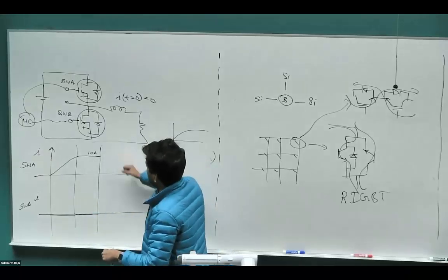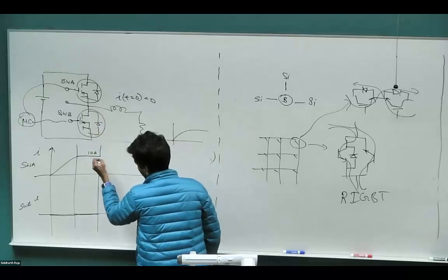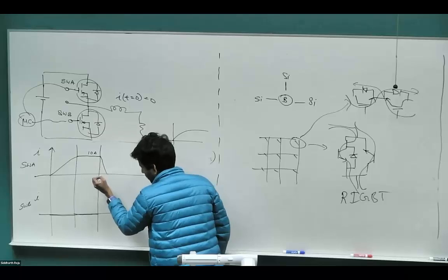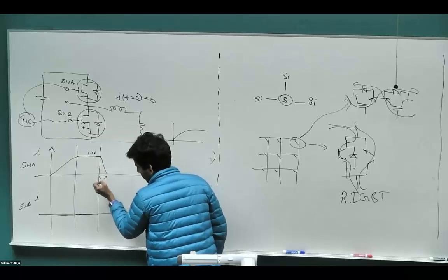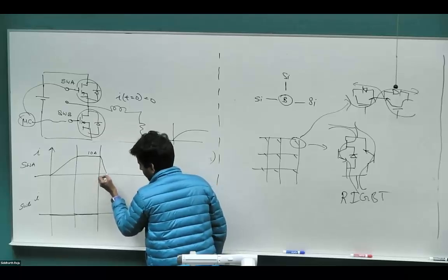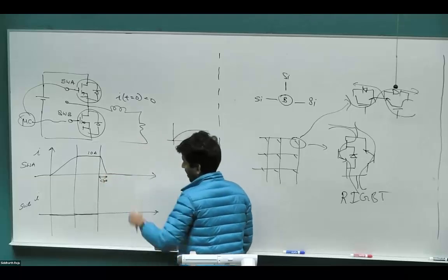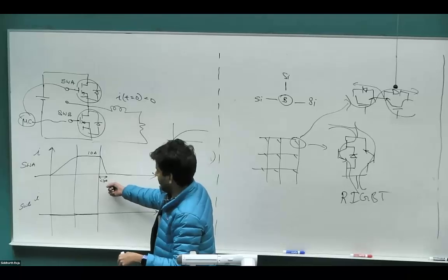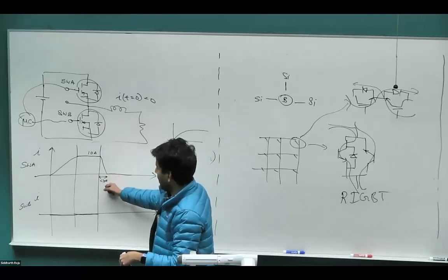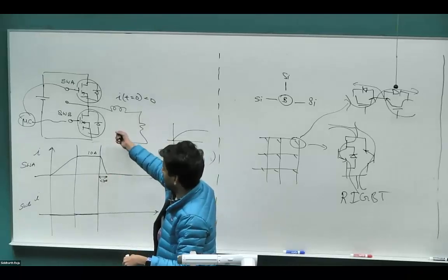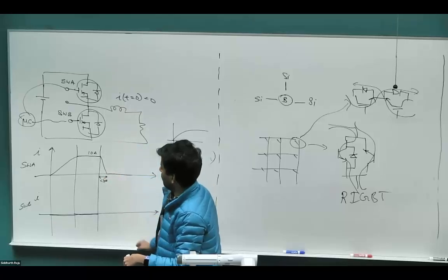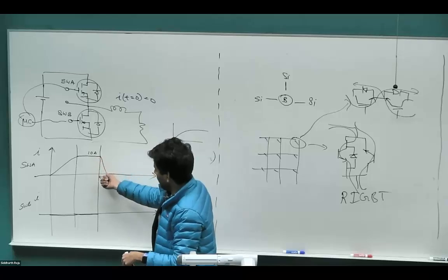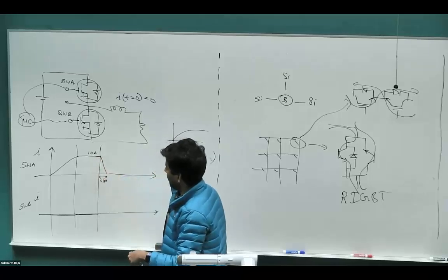All right, so once we turn the switch off, it is going to take some time for the current to go down to 0. And this is again extremely over exaggerated. Typically less than 1 microsecond, and MOSFET it's even faster. High power IGBTs will typically be around 200 nanoseconds or 1 microsecond. MOSFETs are typically for low power applications, silicon MOSFET. So those will have much faster switching time periods.